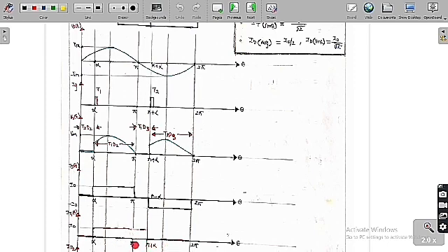in the remaining regions it is not at all conducting, so it is open circuit. So the current is 0 in the remaining range, whereas from alpha to pi plus alpha, T1 is going to conduct. Therefore, the thyristor current of T1 is equal to the load current I naught. So this is the value of the current in the thyristor T1 we are going to get.